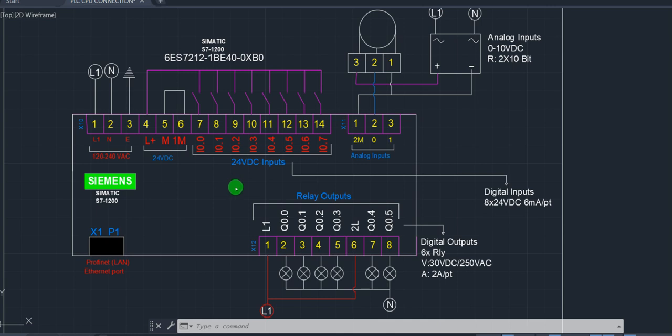Remember that we discussed the power demand of the CPU. Let me make a recap now, please. The power consumption of each of these bits, the power rating, shouldn't exceed the stipulated current rating on the nameplate. Like here, we have 6 milliamp. So each of these bits should not exceed 6 milliamp.